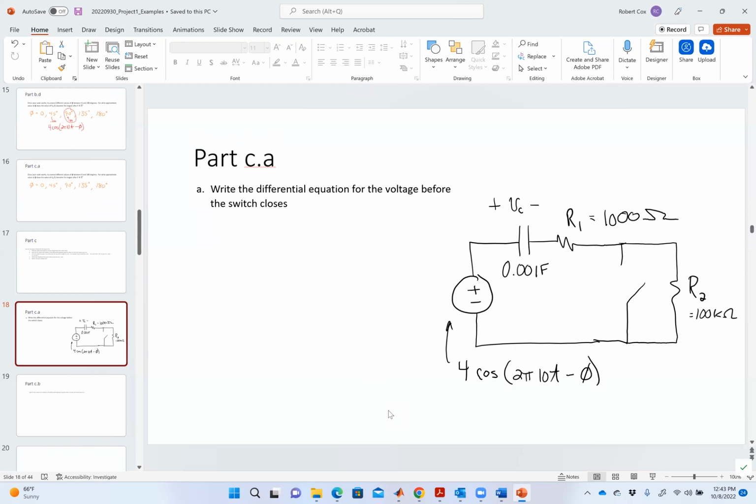This is actually almost the exact same circuit in a way, right? Because what I have now is 2 resistors in series. So really, I could think of it as being the exact same differential equation, right? Vs sub t equal to V sub c of t plus tau, where my tau in this case would be R1 plus R2 times C dV c dt. You should be able to see, right? It's just, I could combine those two series resistors and effectively it's the same circuit. All right, so I get that as my result. So that's a fairly straightforward thing for me to do.